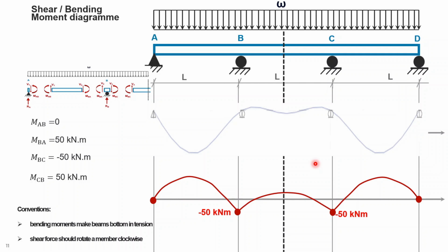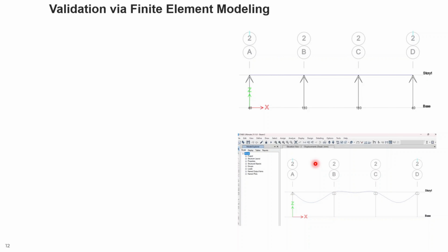see here. And we will do it via the integration method in the next slides, because the slope deflection is only able to provide you with the internal forces and the deflection only at the nodes, and it's very difficult to employ the deflection method if you want to, for example, come up with the deformation at the middle span or at some arbitrary points of the beam. So for that purpose, we will use another method, which is double integration in the next slide.